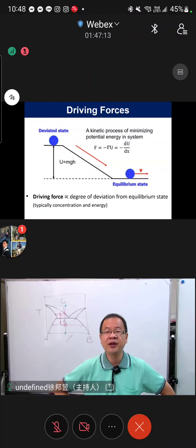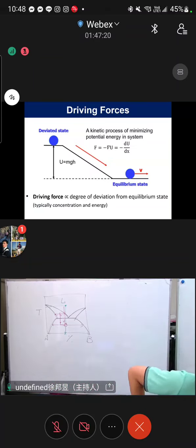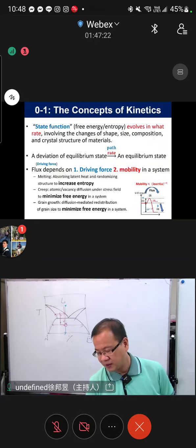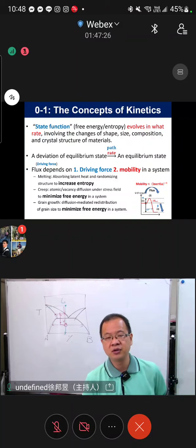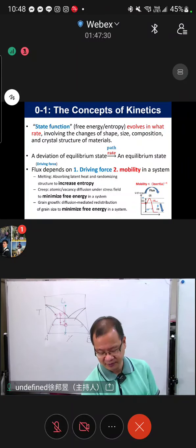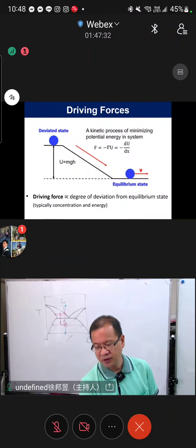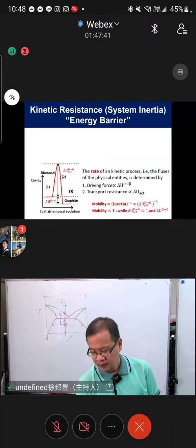But in the crystal, that's the free energy of your crystal from alpha to beta. So try to remind yourself of this bottom right corner all the time. That's a very important picture that covers the most important theory of kinetics. You can use this picture to help your thinking. Atoms need to move from higher energy to lower energy. An easy way to understand it.